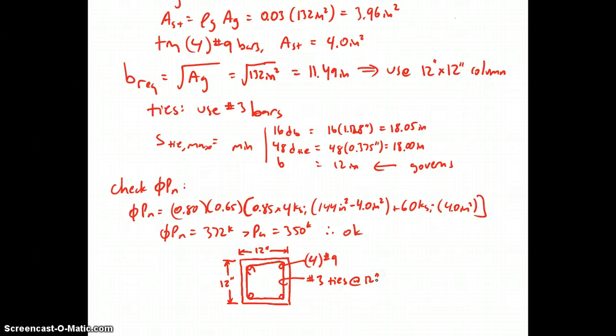Also, we're going to need the material strength to be able to build this, so off to the side we'll label f'c is 4 ksi, fy is 60 ksi, and then finally we'll label our cover, and we'll say 1.5 inches CLR for clear, and in parentheses typical, TYP, to denote that it's 1.5 inches for interior exposure all the way around. So this concludes our initial design of a concrete column, assuming no moment, just axial load.